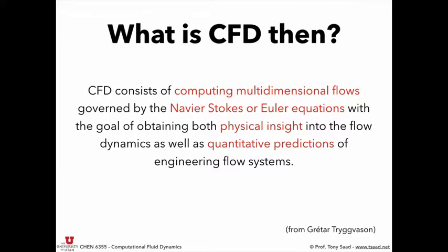There is a certain uniqueness, specifically with the coupling between the velocity and the pressure, and how the pressure can be used to enforce mass conservation. That is unique to the Navier-Stokes equations. That is not found in arbitrary partial differential equations. However, the methods used for partial differential equations are used in CFD.